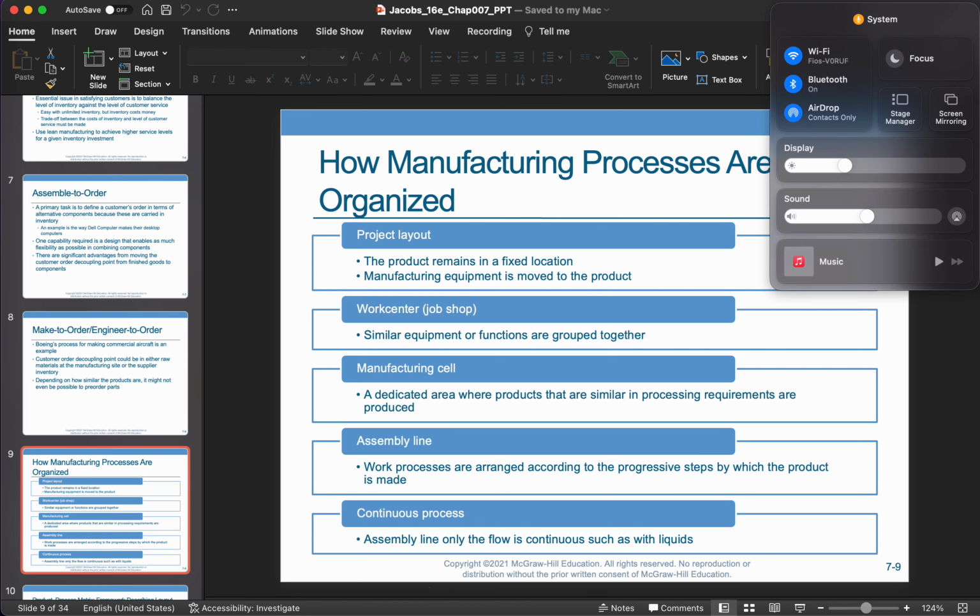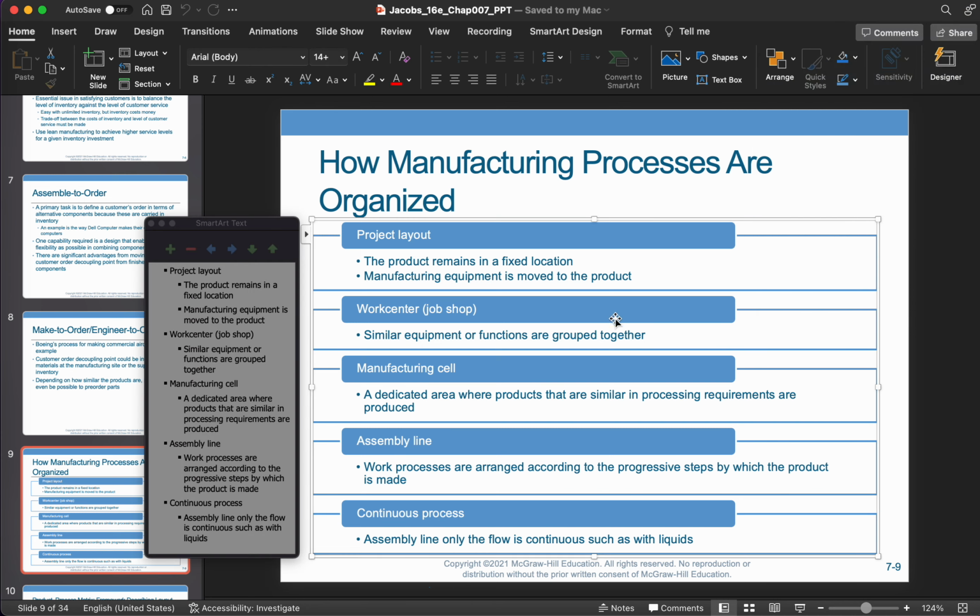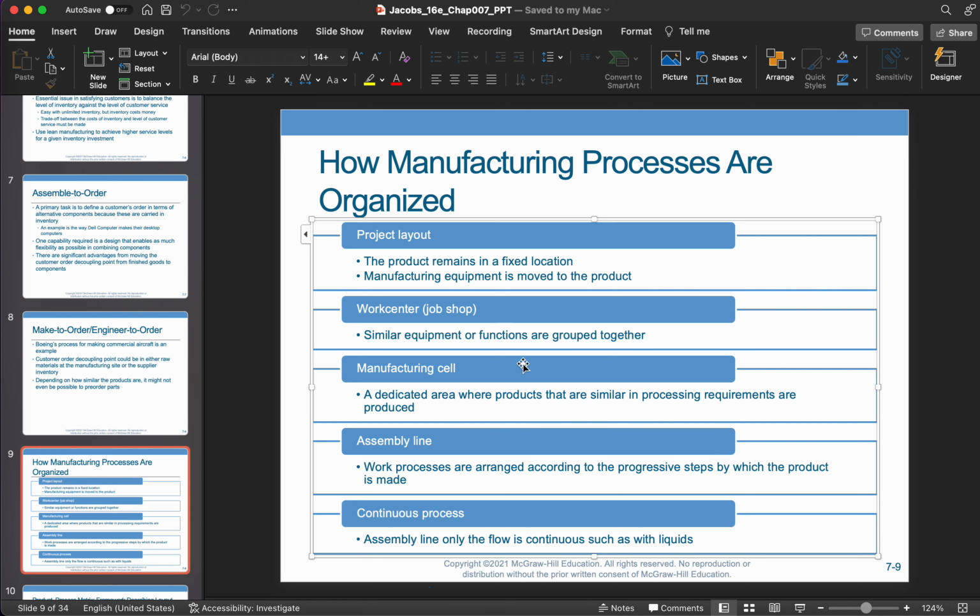So this is where, oops, I'm sorry. So this is where all the machines required to manufacture a particular process are in a particular place. So there's a dedicated area to make a particular product. So let's say that you need one milling machine, two molding machines, and a lathe machine, and let's say a finishing machine and a painting machine to make a particular product. All of those machines are organized into a manufacturing cell, and then all the manufacture for that particular product happens